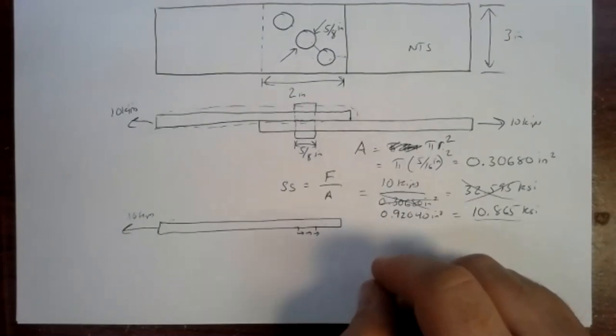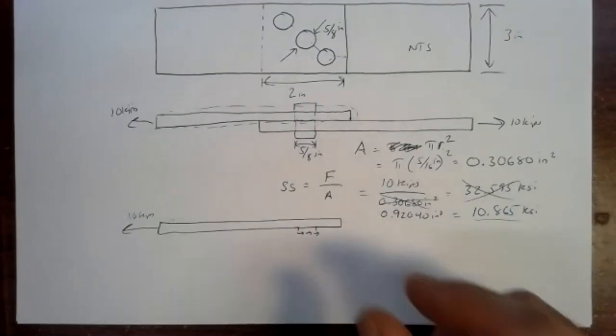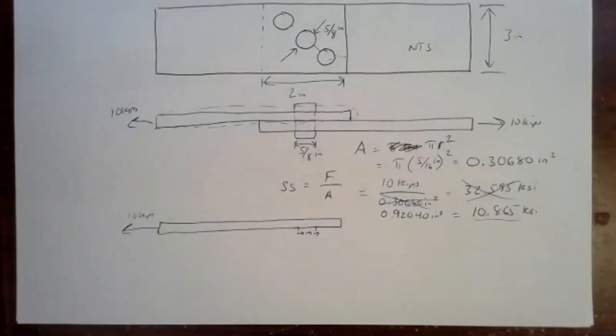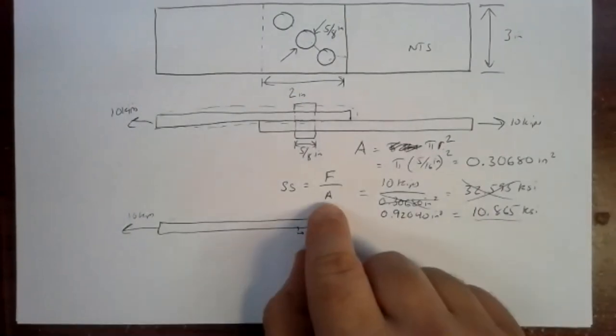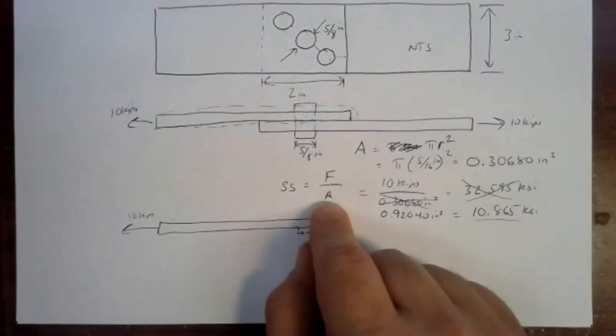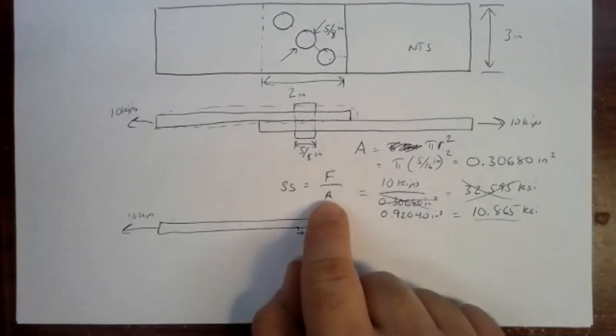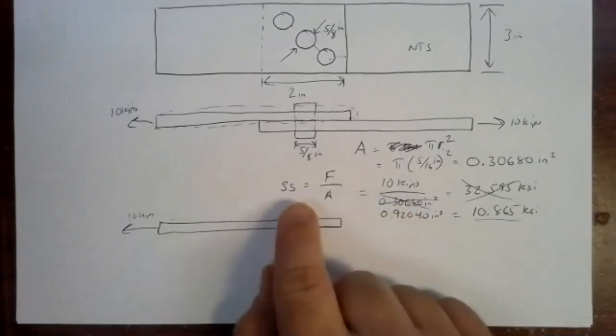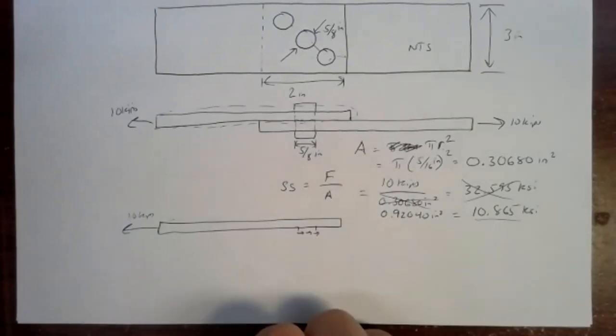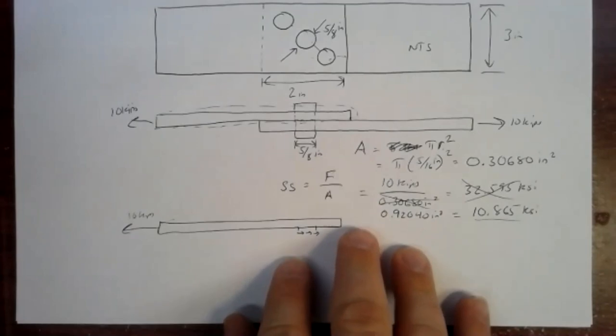Well, if I'm using an 1/8-inch rivet, I know how many square inches that 1/8-inch rivet is. That's the area of one rivet. And then you divide that into the total area you need to tell you how many rivets you need. Round up to the next highest rivet, and you're good to go. So that's basically how the rivet calculations work. We figure out the minimum number of square inches of area we need to support that load without breaking things. And then we calculate how we can spread that out over a particular size rivet, whether it's an 1/8-inch rivet, whether it's -4, -5, -6 rivet. So that's shear stress there.